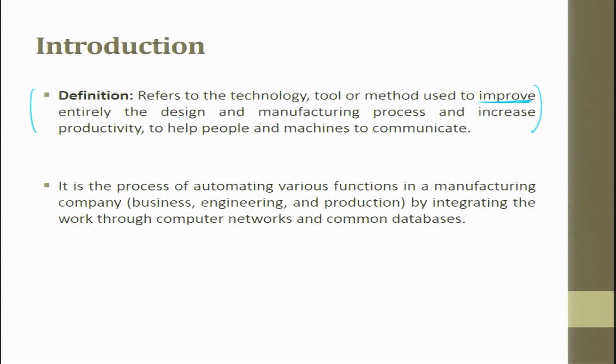Designing means there has to be a calculation involved, an optimization involved, an iteration involved. For example, you decide to use a nut and a bolt in an assembly. First you have to decide what size, M1, M2, M3, M4, which one to choose and how to fasten. For that we have to do the design.